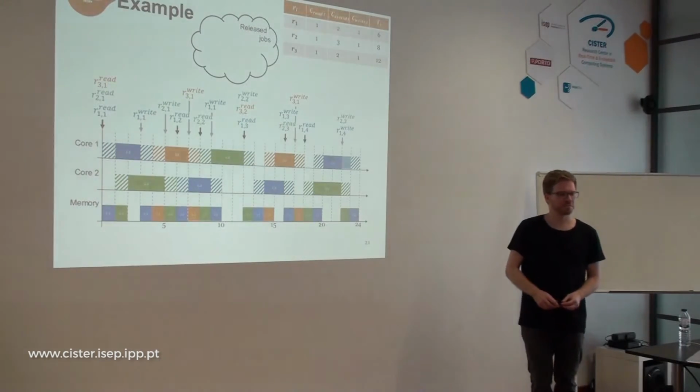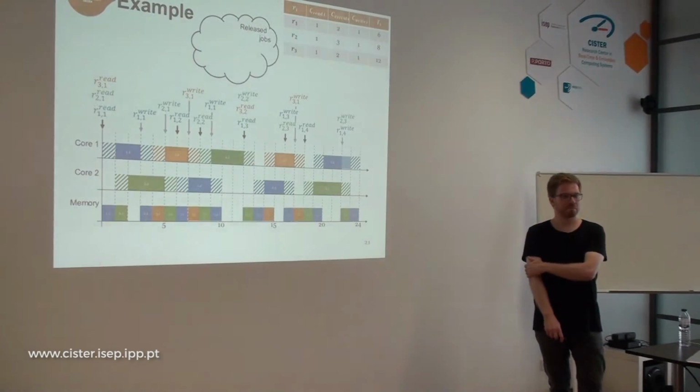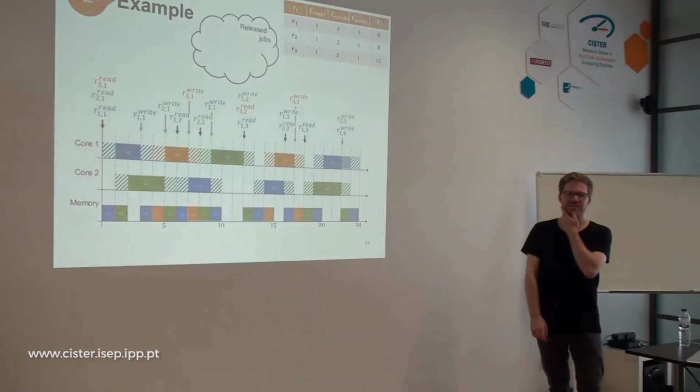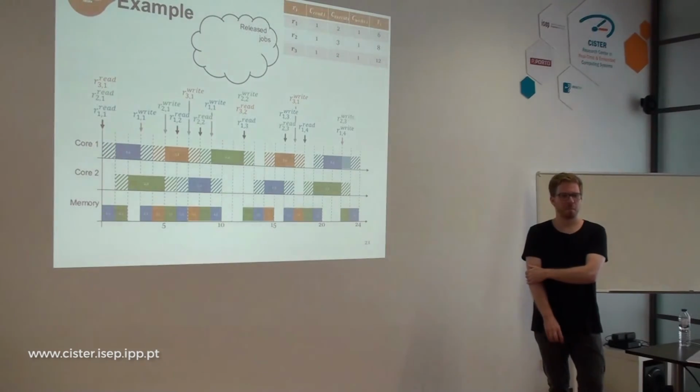Maybe what we could do, apparently if you use more than 8 cores, it's not very useful. You don't gain anything in terms of performance for this specific use case. So maybe we can just disable 8 cores, and with these 8 banks, we can use 1, or 2, 3, or 4 for the labels, and then we could also use 1, 2, 3, 4 to preload the code of the runnables which are about to be executed.